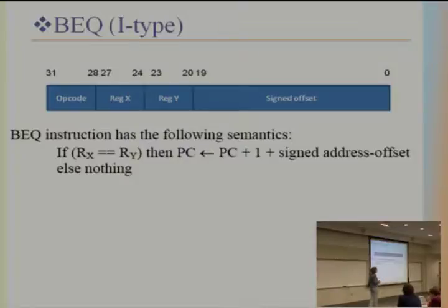That's true. So obviously our finite state machine will have an optional branching. And if, let's say, it's true, if we need to do this, then we need how many steps? 6. And if we don't want to do that, 3. Yeah. So why do we need? Well, we need definitely one step to read Rx, and we need one step to read Ry, and then we need a step to ask, is it equal?